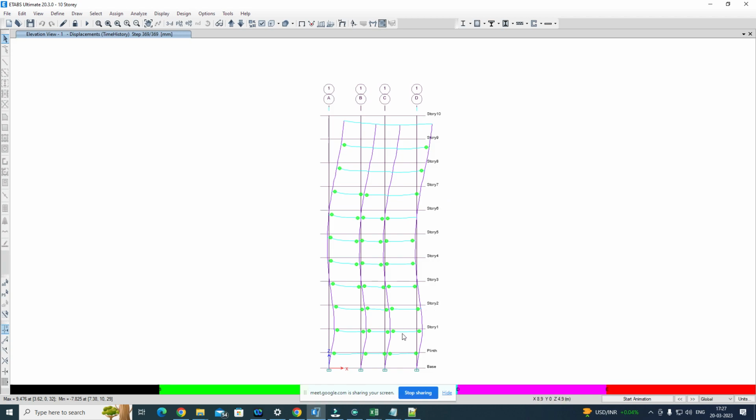So till that point, what you can see is this green zone, which is between B and C, sorry, B and D. Here you see D and here it is B. Then D to E it will show in, I think, pink color or something, and then you will have the red color. Now see at this point you do not have any pink or red color, you have only green, which means all the hinges are performing within B and C of the backbone curve.